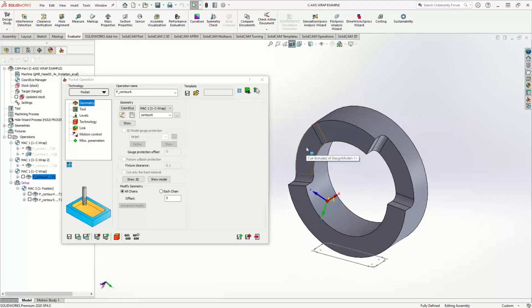But yes, exactly. What you could do here also is if this was not a pocketing toolpath, but a profiling toolpath, you can still use the wrap geometry despite the fact that they're open. If you were trying to close this pocket, then to Kevin's question, I would probably either sketch something or I would use point-to-point and just try and close that gap. Because remember, when you do wrapped, everything becomes wrapped around the x-axis, or whatever axis you choose.